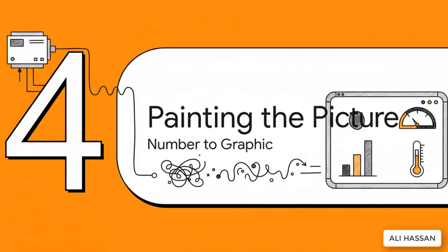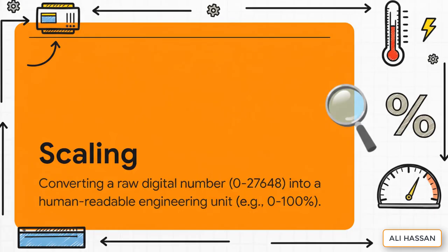Okay, so the PLC has its number, 27,648. That's fantastic for the computer, but it's completely meaningless to a human operator. So the final step in this journey is to translate this raw number into something we can actually understand on the screen. This whole process is called scaling. And really, it's just a translation. The PLC takes that raw machine language number range, 0 to 27,648, and it converts it into a human-friendly range, like, say, 0 to 100%, or a temperature in degrees.